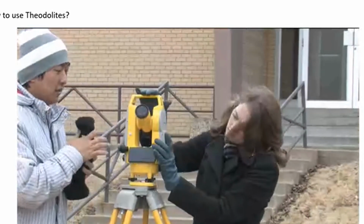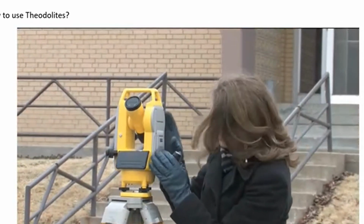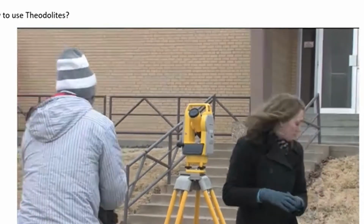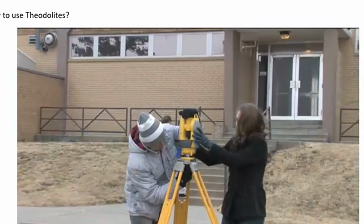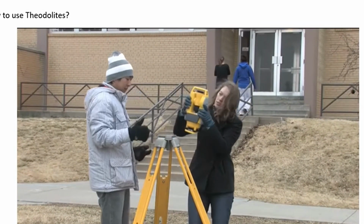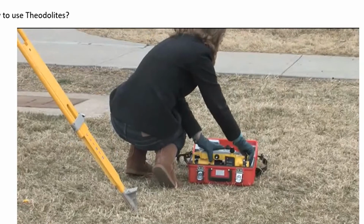This completes the process for angle A, B, C. Continue on for each subsequent angle on your traverse polygon. Once the team is done with the instrument, place the lens cap back on the scope and remove the batteries. Gently remove the instrument from the tripod and return to the case. Remove the tripod from the ground, collapsing it, and picking up any trash that you may have accumulated in the field. It is now time to start the calculations.